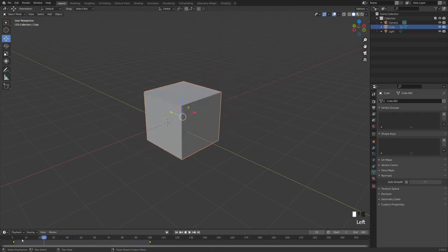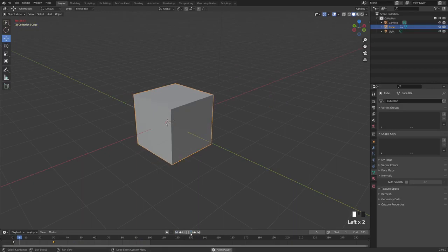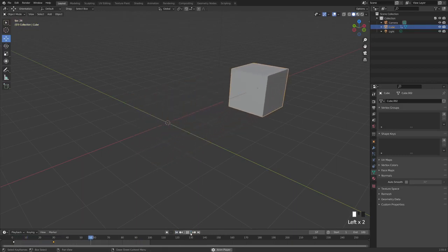You may notice that these keyframes are highlighted orange. That's because they're selected. If I click in here, I can deselect them, and I can actually move these keyframes. So I'm going to click and select to drag this frame, and then I'm just going to click and drag to move that frame to 30, and that will make my animation play much quicker. So if I hit play, we'll see that now it snaps there in 30 frames.